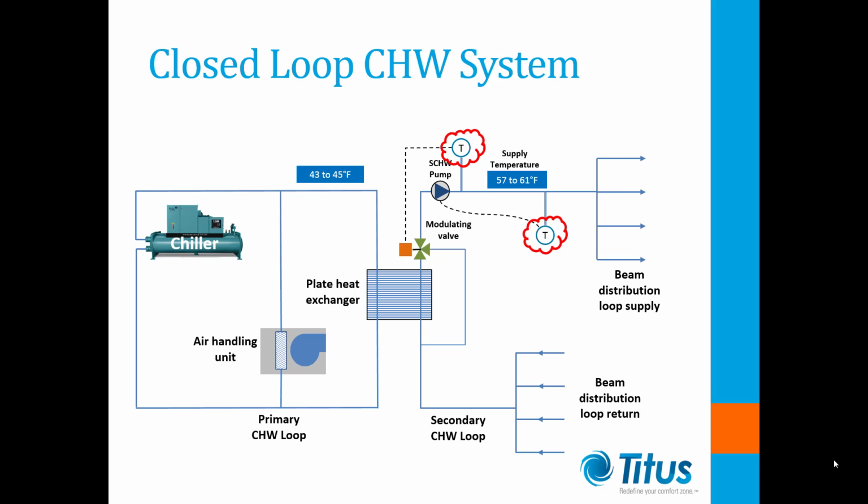and the second sensor is used for a thermal cutout circuit which shuts off the pumps if low temperature chill water is detected in the secondary loop. This ensures condensation will not occur on the chill beam cores in the event of a system failure or operator error.